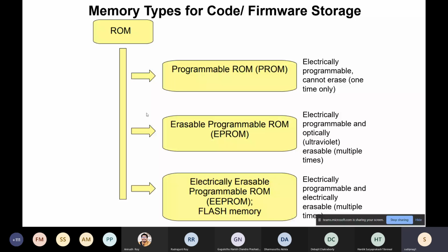You must be storing some user data, such as what should be the RPM of each of those motors, what should be the accelerometer readings for stabilization while it is in the air or while it is taking off and just coming down to the ground. Those kinds of user specific data are typically stored in the EEPROM.